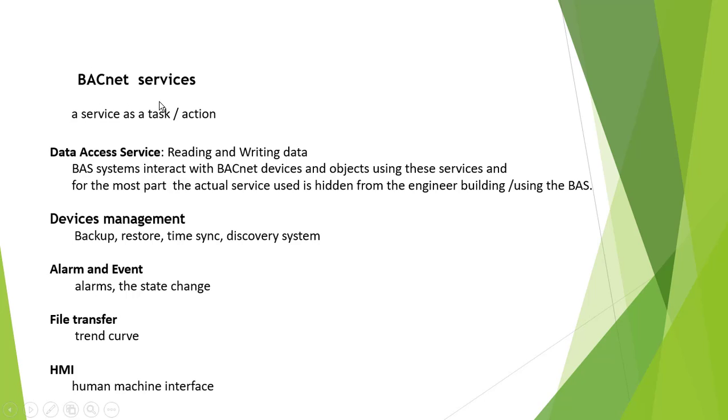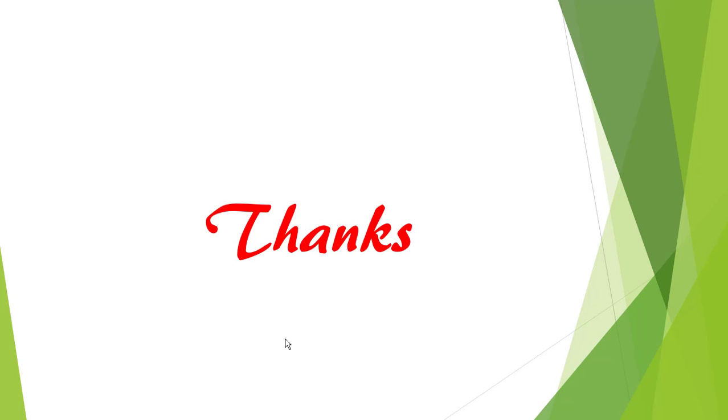All these BACnet services are simple, just talk. It's reading and writing data from one object to another object. It's just backup and restore of the information. It's just alarm events. If there is an alarm, it creates an alarm event, and we can check the trend curve and use the HMI to watch everything and control something. This is BACnet service.